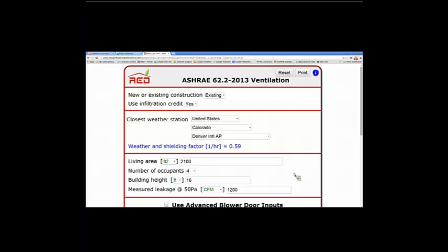But some code officials are still thinking about that and might remember hearing an openable window does not qualify anymore as ventilation of a bathroom. But the ASHRAE standard 2010 and 2013 versions, Appendix A, does give you 20 CFM credit for an openable window.